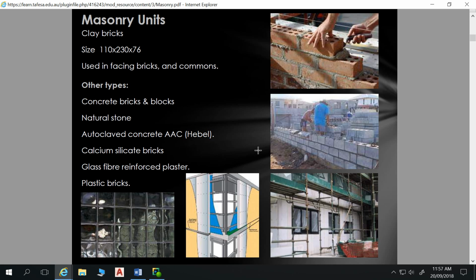And you can see with these concrete blocks here, we've got some reinforcing poking up through there. So that tells me that this is going to be core-filled for at least those cavities. So we've got one, then missing two, then another one. At 390 a block, let's try to work out what our spacings are. So that's at 600 centres. So all that reinforcing is happening at 600 centres. So every third cavity will get filled with concrete.